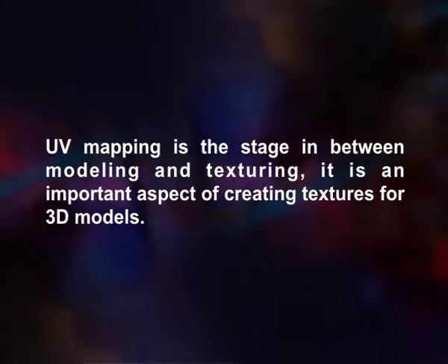It is an important aspect of creating textures for your 3D models. Creating a good UV layout allows us to tell Maya how to apply the 2D texture images that we create. If UVs are not present on an object or polygon primitive, you cannot see the mapped textures. This happens if you inadvertently create a primitive object with the create UVs option turned off.